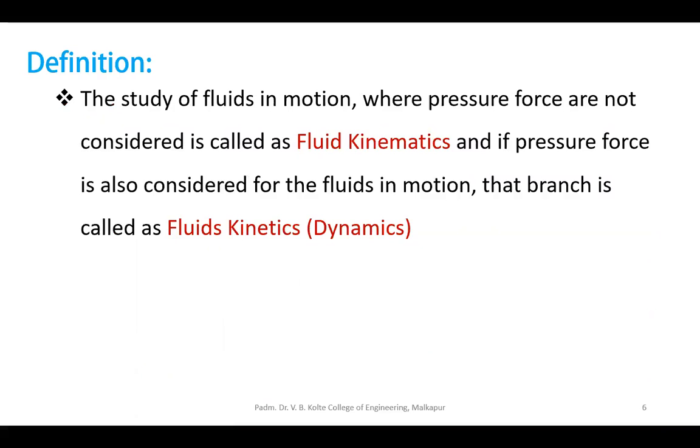So next is what is meant by fluid kinematics and what is meant by fluid kinetics. So fluid kinematics and kinetics, we already studied that they are the branches of dynamics. So the study of fluid in motion where the pressure forces are not considered is called fluid kinematics, and if the pressure force is considered, then it is called fluid kinetics. Okay.